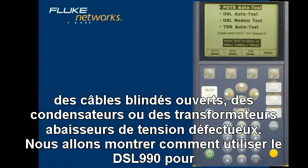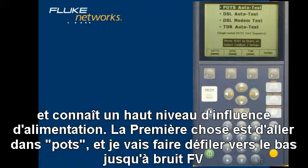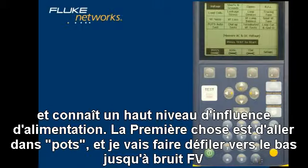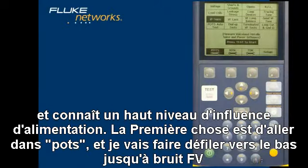Okay, what I'm going to do now is show you how to use the Copper Pro to analyze noise problems on a pair. I've got the Copper Pro connected to a pair that's about 1,300 feet long. This pair has a tip ground problem, and this pair is also suffering from a high level of power influence. First thing I'm going to do is go into the POTS toolbox, and I'm going to scroll down to VF noise.